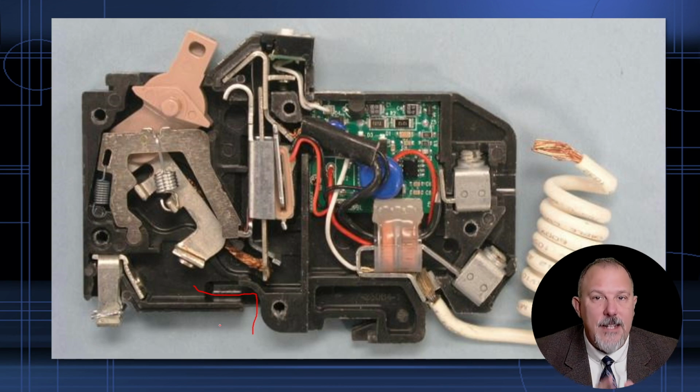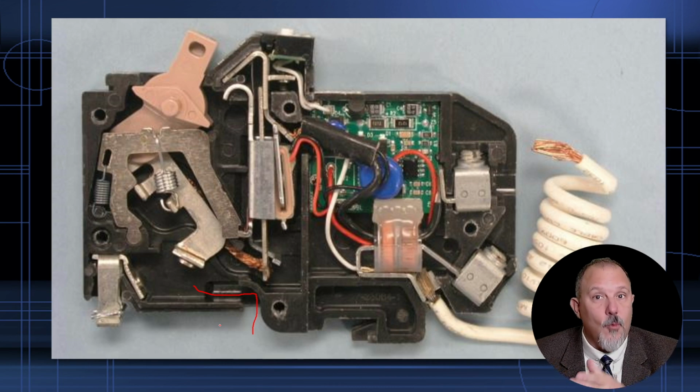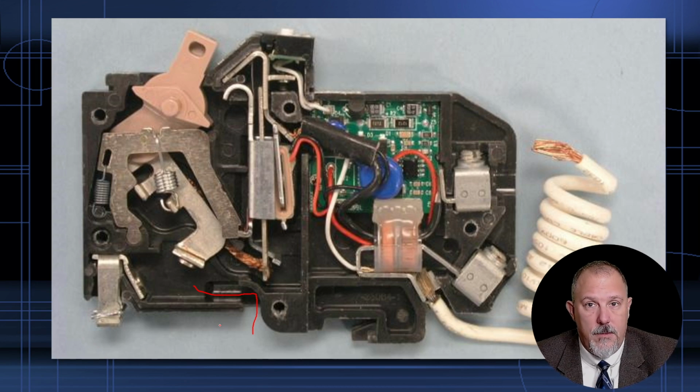The arc extinguisher is a device that you will see in larger circuit breakers. On your standard 15, 20, 30 amp molded case breakers, especially your single pole and two pole breakers in a residential type application, they don't have arc extinguishers. I don't need them.